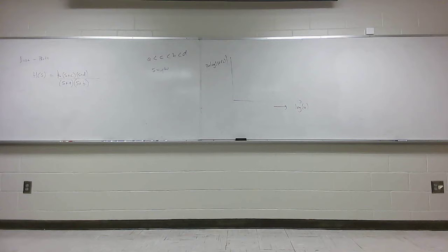When you look at this, and I take 20 times the log of this, what do you know? When S is a very small value, you really have 1 downstairs, don't you, class? And then when S is equal to 1, you have really the square root of 2 in magnitude, don't you?